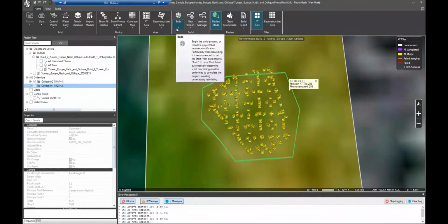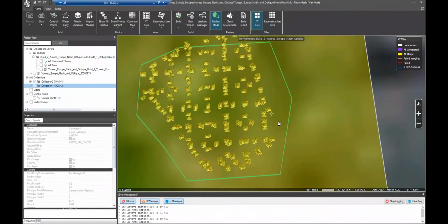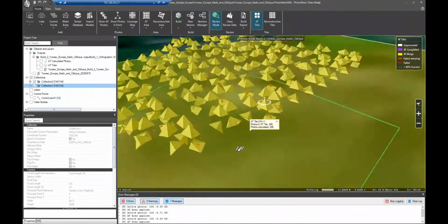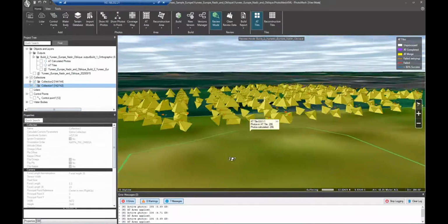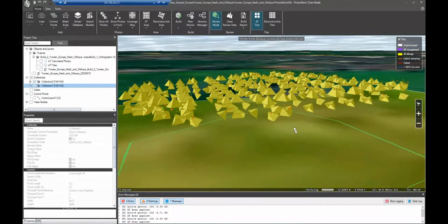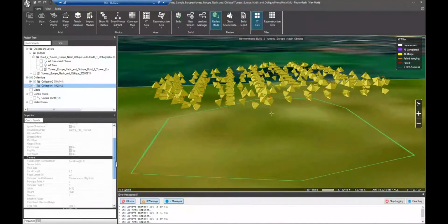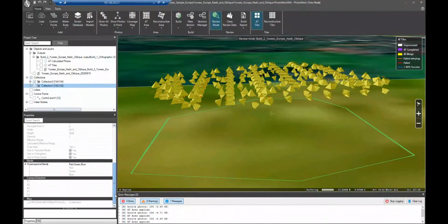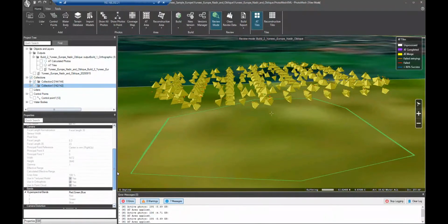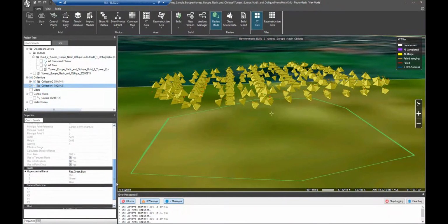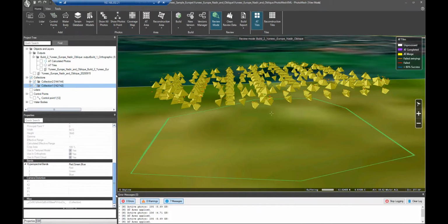One thing to consider, you could see that sometimes if the images don't have very accurate GPS, they come in at 2 different levels, because the Z value might not be perfect. So that's pretty common with drone data that doesn't have PPK.